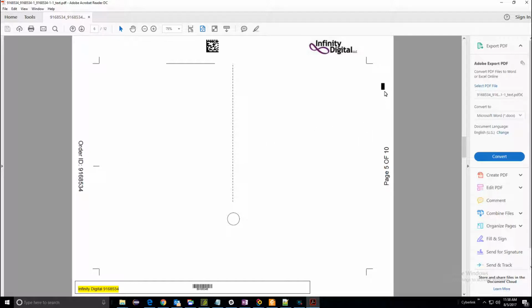We have our eye mark that we placed over here, which represents a typical press registration mark that you might see. And then lastly, we have our drill mark, which we placed down here below the fold mark. And again, the only big difference with the drill mark compared to these other press marks is it has an attribute for specifying the diameter of that. So that covers all of the 6 press marks that you can add to a layout. So this video is starting to run a little bit long, so we're going to go ahead and end this one here, and I will see you in the next video.